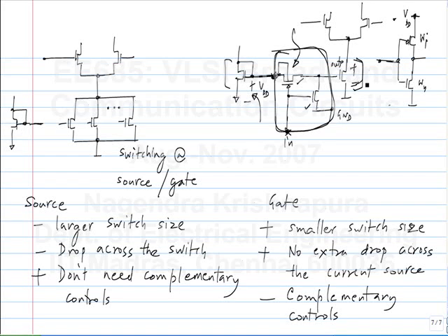The only thing that would govern the size of this is you have some capacitance here, and the rate of charge of this capacitance depends on the size of this transistor, because this acts like a resistance and it can rise up very slowly. So if there is a constraint on that, you may have to increase it from the minimum size. It depends on the absolute value that you need. If you have a very large transistor here, it may take a very long time to charge up. Okay, we'll stop here today.